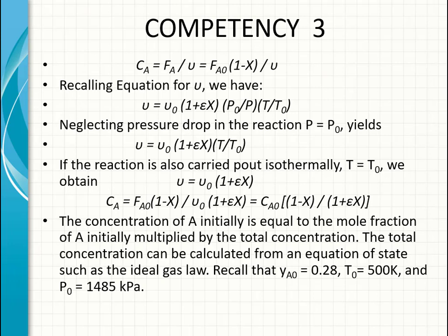If we recall the equation for the volumetric flow rate as a function of the volumetric flow rate at time equals 0, v equals v0 times 1 plus epsilon X times P0 divided by P times T divided by T0.